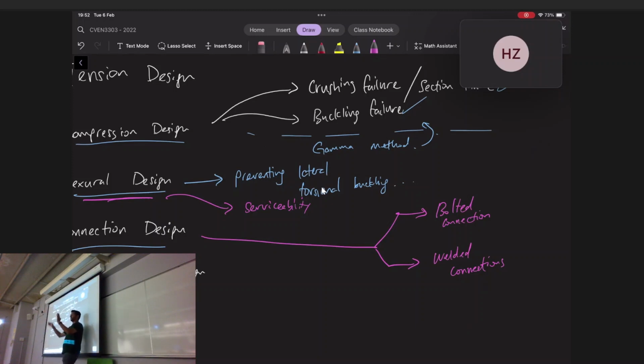imagine you've got a part of a building that connects a beam to a column, right? If you calculate the strength of the column and you're like, okay, I know how strong the column is, it'll be fine. And you calculate how strong the beam is and you're like, yeah, the beam is going to be fine, this building is going to survive, it's awesome, let's go get drinks, right? If that's the situation, but you did not design your connection properly, then the weak point of the building could be your connection, right?